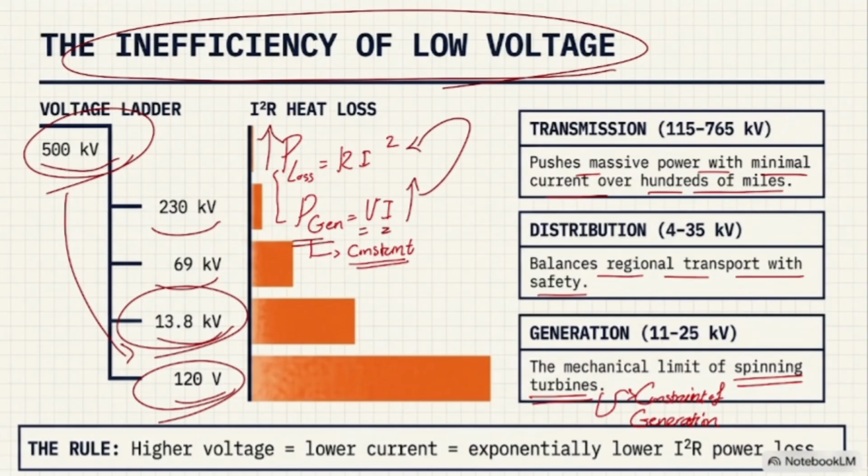That's why I'm trying to convert this voltage to something higher in order to reduce the amount of current. And this current, due to the transmission part, which is going to be 150 to 765 kV, is going to be reduced, and we do have less loss.